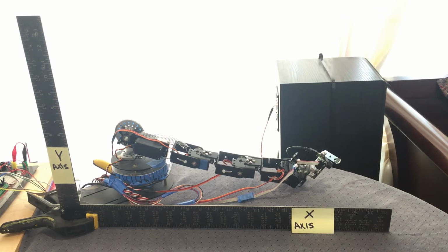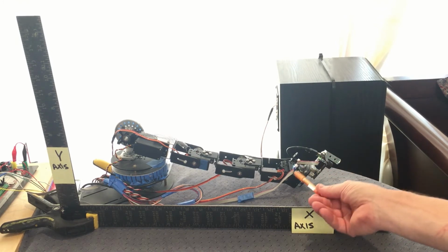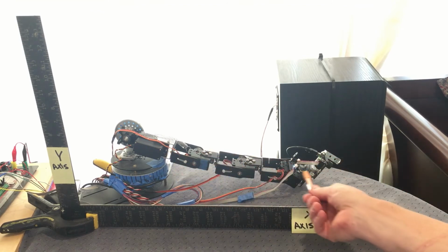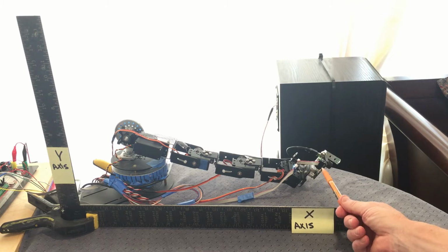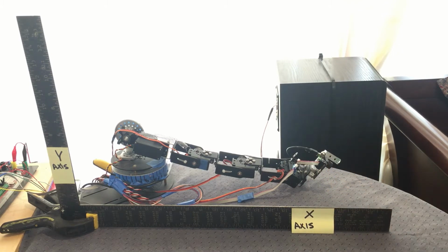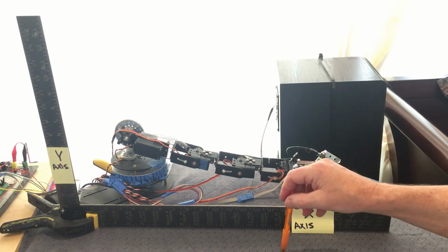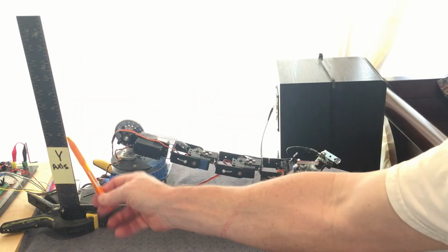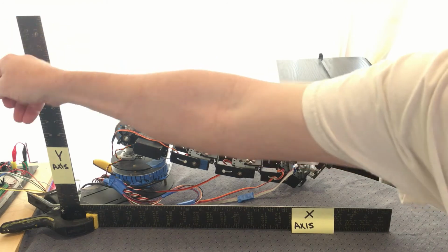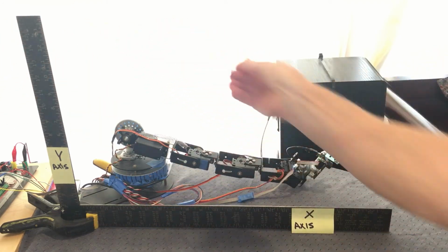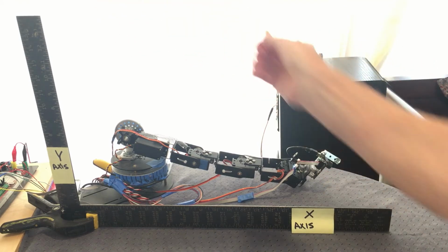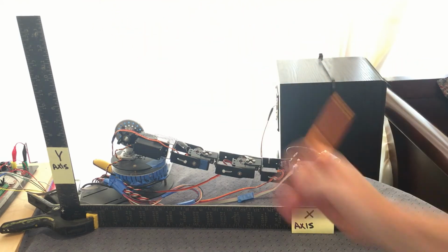6, 4, and 4. My longest distance will be the sum of that, which is 6 plus 4 is 10, plus another 4 is 14. So anything at, say, 15 and longer, I can't reach. Anything below the table, I can't reach. And anything on the other side of this y-axis, greater than 90 degrees, I'm not going to deal with or reach either. So it's very limited. It's an arc in this area only right here.